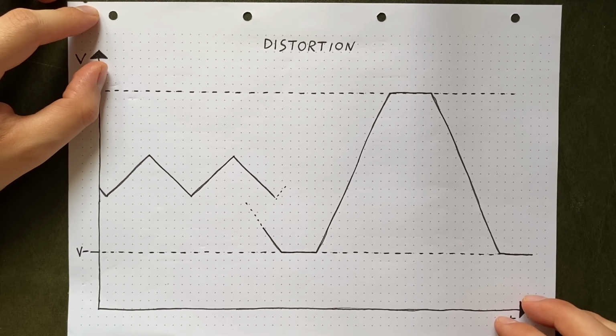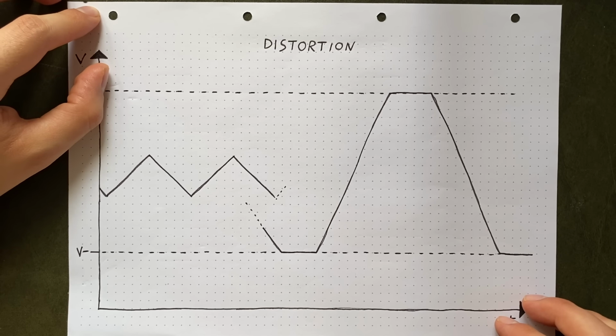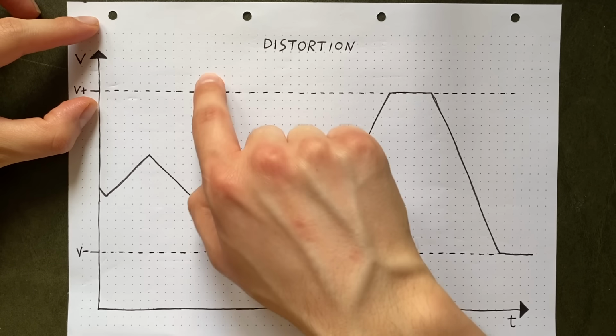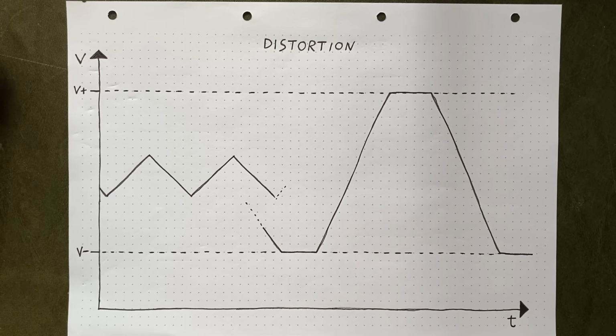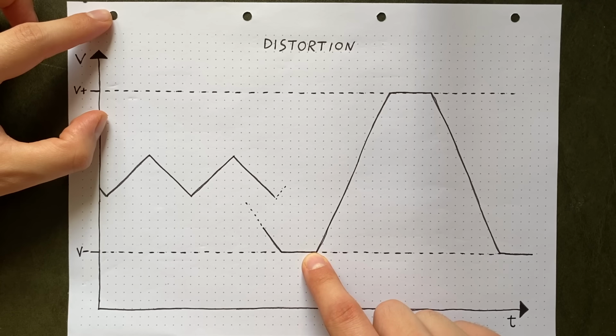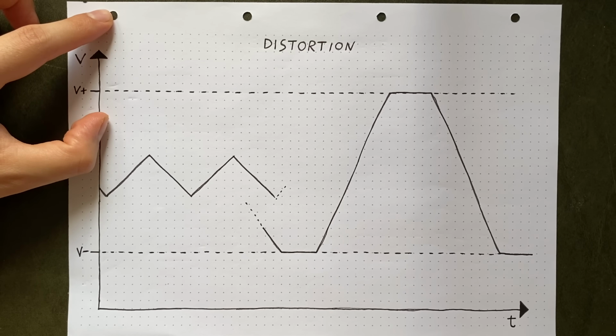Okay, but why is that necessary for our buffer? Well, it's mostly to prevent distortion. Op-amp buffers do just fine when they have to copy voltage levels that are comfortably in between their positive and negative supply rails. But if those voltage levels get close to those rails, the buffer can't accurately reproduce them anymore. So while we could just hook it up to our positive and ground rails, we should instead use positive and negative rails, just to provide it with enough headroom and prevent distortion outright.